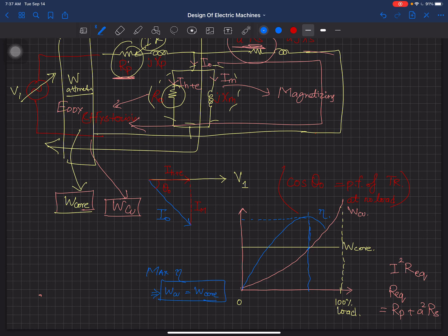At this point, the maximum efficiency is there. And for this particular reason, now listen to this very carefully, whenever you have the copper losses in a distribution transformer, you keep those copper losses and the core losses somewhere near that 70% mark every time, because the distribution transformer, when it is working for 24 hours a day, for major time,